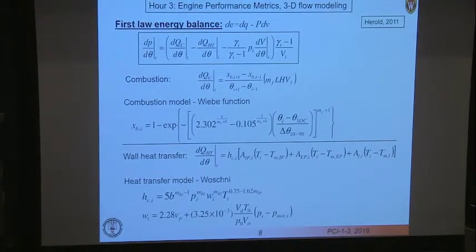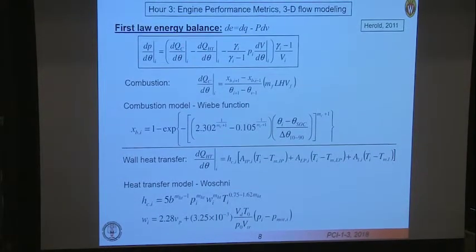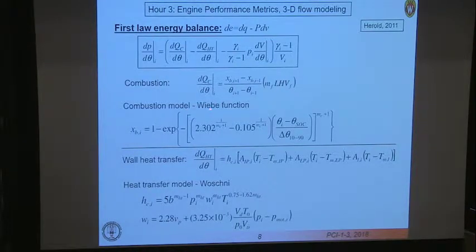So combustion, how do I model combustion? I need this dQc/dt, the rate of heat release with crank angle. At time i, I'm going to use what's called a Wiebe function, which is essentially a curve fit of experimental data on combustion rates, in this case, spark ignition engines.